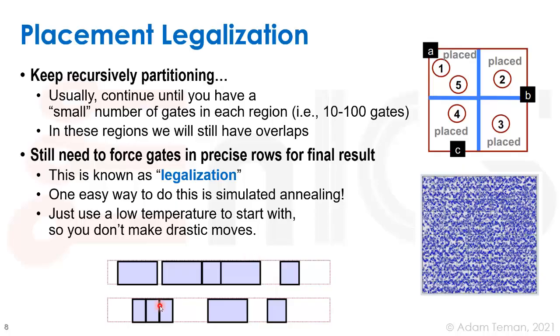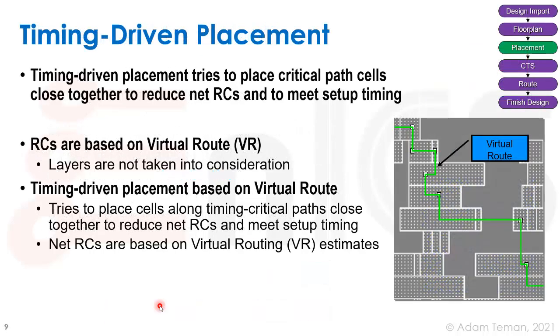And let's go back to this one too. So timing-driven placement. Everything we talked about was optimization of the wire length. Wire length is really nice, but everything we talked about in our previous lecture on static timing analysis was that we're trying to meet constraints, that the main constraint is timing. And how does wire length relate to timing? Well, we think it is proportional, and that's why we use wire length as a metric. I mean, because of timing, because of area, and so forth. But it is not correlated one-to-one.